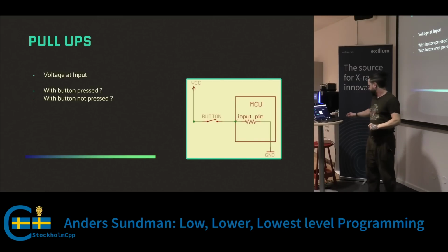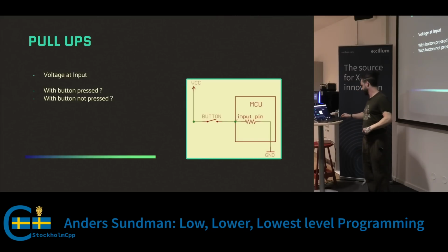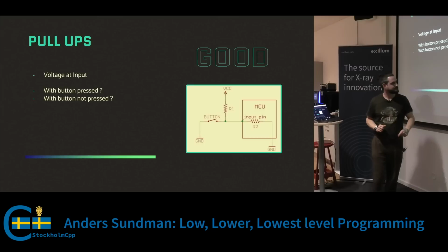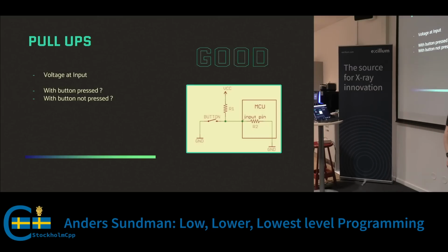What your electrical engineer should do to fix this is put a much smaller resistor here, a pull-up resistor, connected to power. If it's open, this is a voltage divider, and this one is very small, so it's insignificant in comparison with the other, so it's like the supply voltage. If it's closed, then you have 0 because it's a direct connection to ground.